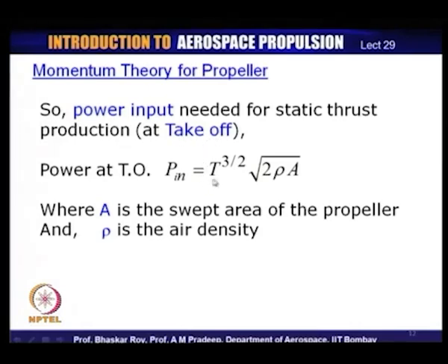Equally, the thrust created by the propeller during the takeoff is likely to be one of the highest thrusts required during the aircraft flight. So, the highest power and highest thrust creation of the propeller quite often is asked for during the takeoff. The power required has to be supplied by the engine, and only then would the thrust needed for takeoff be possible through the activation of this propeller. So, this power supply estimation is extremely important because that allows the propeller to match with the engine.